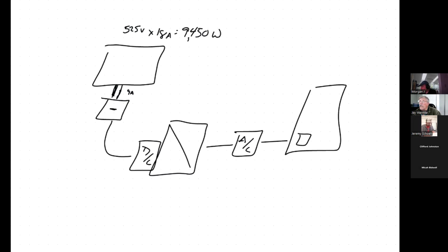But when you're looking at this table, I want you to get in the habit of only looking at column 1 for your ampacity. Go with the lowest case because your connection is not only the wire, but it's the terminals on each end of that wire as well. And those have temperature ratings, and you don't necessarily know what they are.